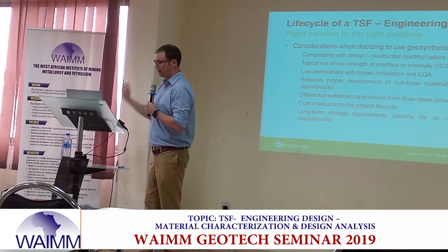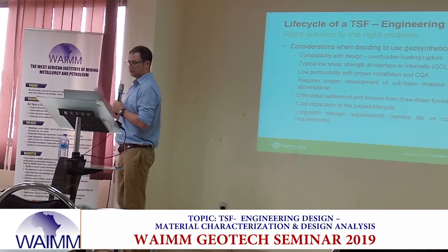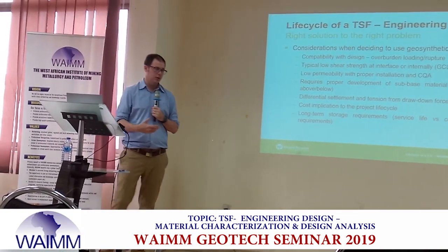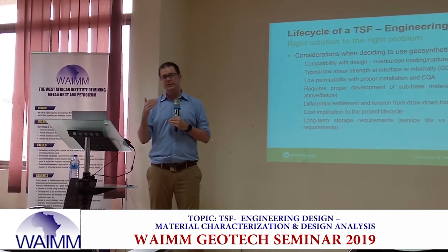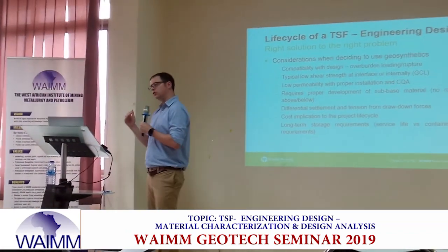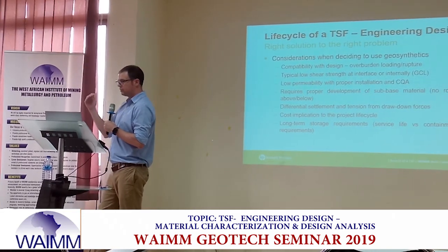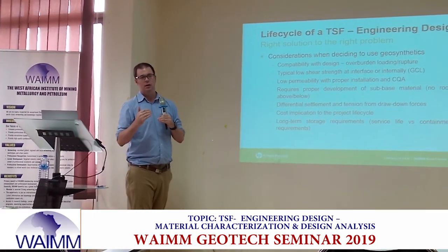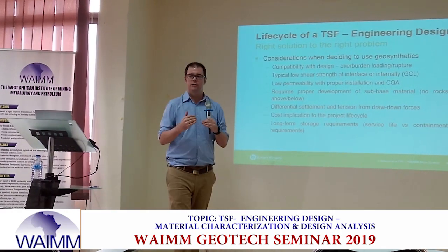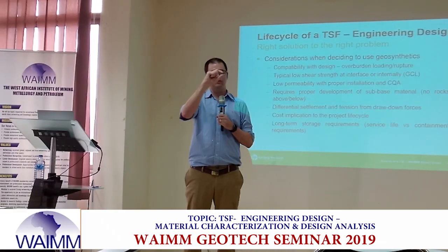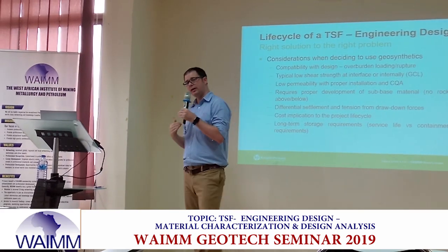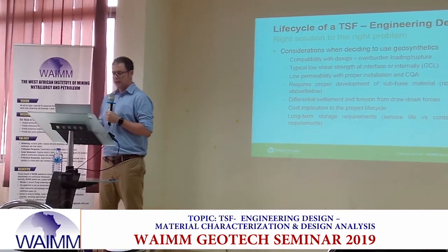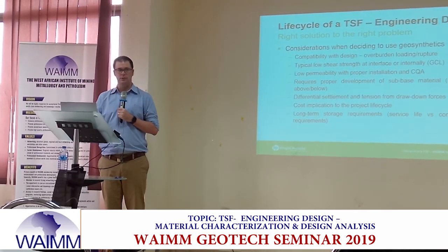We need to have proper development of subbase to prepare before we put down a geosynthetic. We might have differential settlement issues. Again, the nice thing with a thick layer of clay is if you do have some settlement, if you do have some deformation, the clay can actually accommodate it. It's not brittle. Okay? It doesn't tear. Where geotextile, geosynthetic is very, very thin, and if you do have that differential, it may strain enough that it actually tears. There's also things like cost implications.